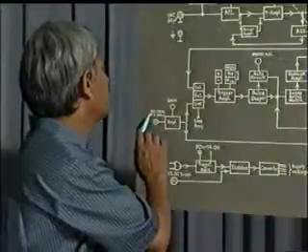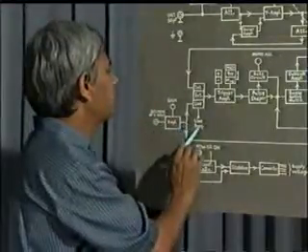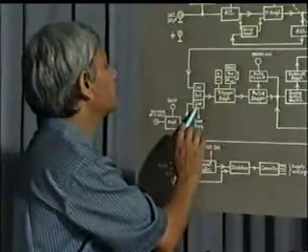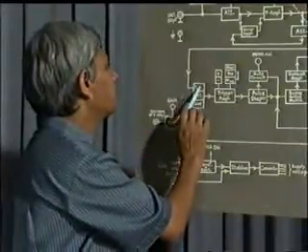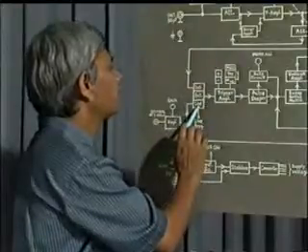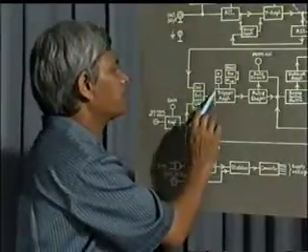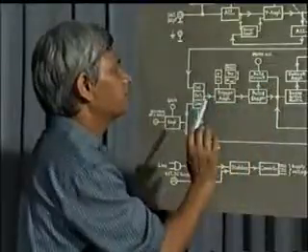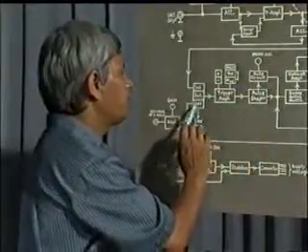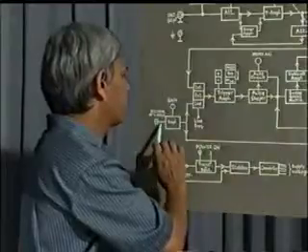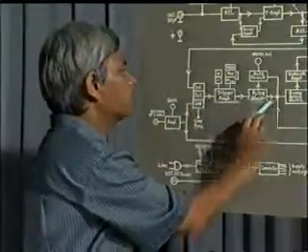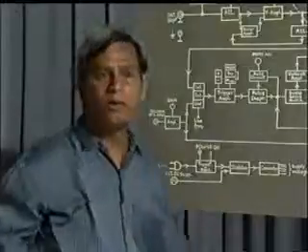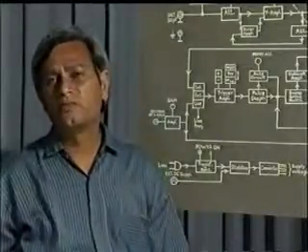This is the external trigger input and this is the line frequency in. You can select either internal or external or line mode for triggering this trigger stage. And seeing the wave shape starting from here to here, you can find out where the pulse is missing. In this area, the problem may be less in the circuit section but may be more in the band switch edge.